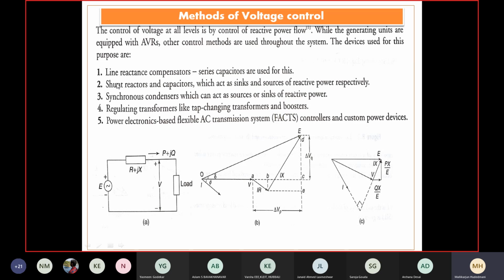As we were discussing in the earlier point itself, a highly inductive transmission system, or a transmission line delivering power to a highly inductive system, definitely suffers higher inductance, because of which the inductive drop is more, and the lagging concept is identified in that. To improve upon that, if I adopt a shunt capacitor, it will improve the power factor of the current flowing on the line. So use of a shunt capacitor is another concept at the point of load.